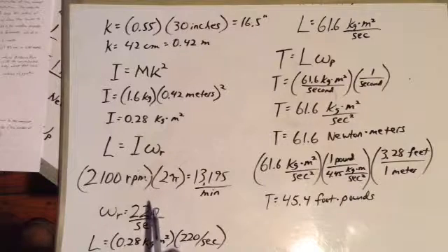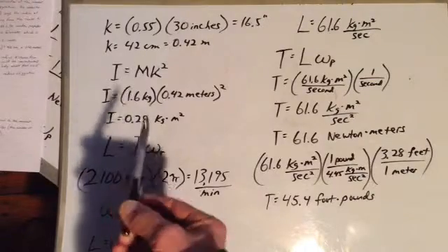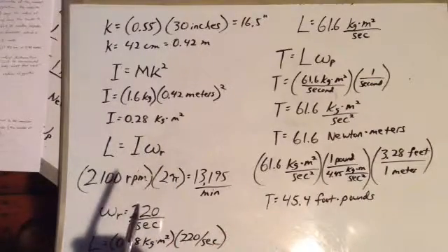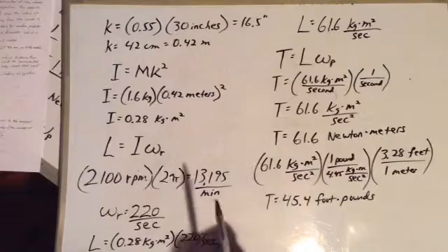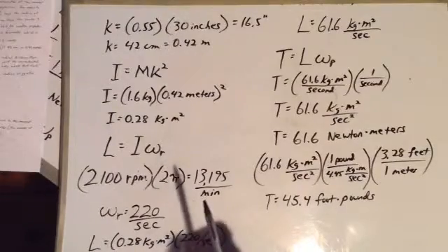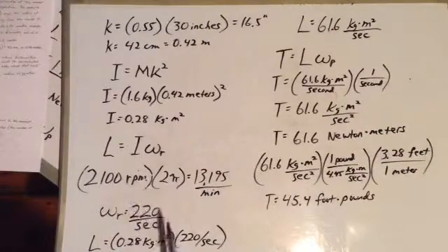If we do a power on stall with a propeller spinning at 2100 revolutions per minute and the nose of the airplane plummets 1 radian, 57 degrees in 1 second, then the resulting gyroscopic torque will be, let's see, uh-oh, I skipped something here. So let's get back to our angular momentum.